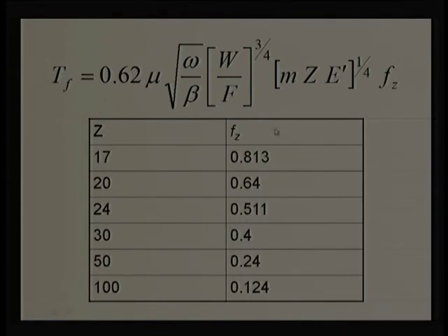That is why we try to utilize a lot of this kind of analytical expression or curve fit expressions. If we require detailed calculation, it will take many iterations. So, if we are designing initial level gears, we should always recommend this kind of curve fit equation: find out the TF, find out the viscosity, again find out what the load carrying capacity will be, what the H minimum will be, because H minimum itself is going to depend on the viscosity, and H minimum is going to affect the mu, and mu is going to affect the TF.